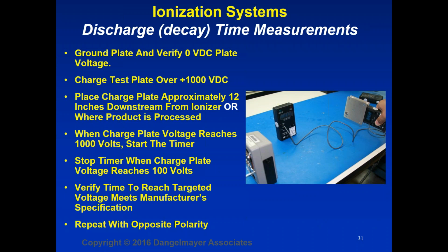Another question, Arnie. Is the standard requirement of plus or minus 35 volts a requirement or user-defined? Well, we're actually going to talk about that, I think, towards the end when we talk about 2020 changes. The requirement in S20.20 for ionizer balance of better than plus or minus 35 volts is connected to the notion that the ionizer is going to induce voltages on isolated conductors, which it will do. The voltage that the ionizer will induce on that conductor is dependent upon the conductor's distance from the ionizer. It's dependent on the conductor's relationship to ground.